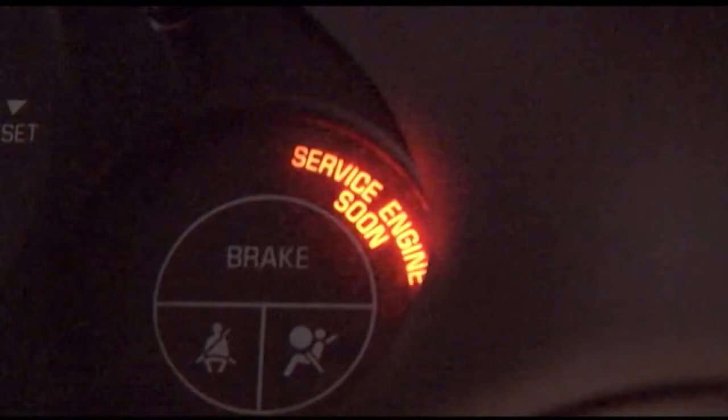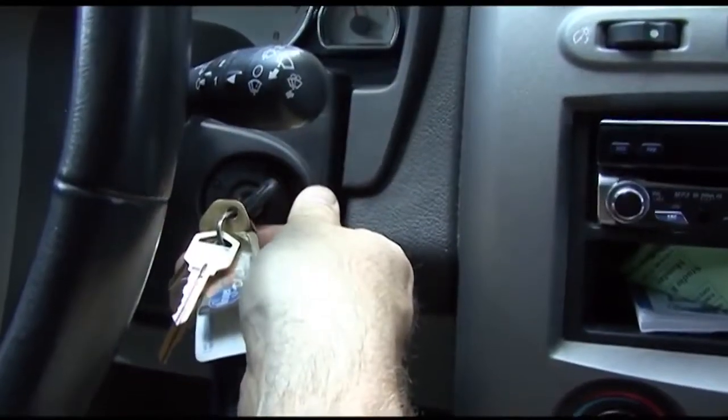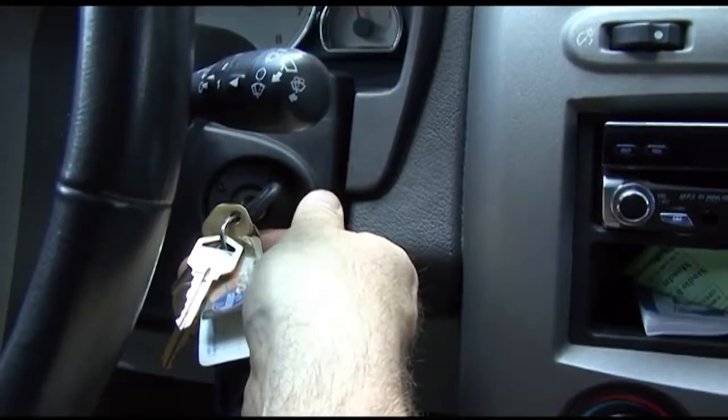Now, let's talk about how you should investigate a no start. The first step is to check and see if the check engine light is on when you turn on the key. Next, check to see if the theft deterrent light is flashing. Can you hear the fuel pump run for 2 seconds when you first turn the key on, and then again after you start to crank the engine? If everything checks out so far, move on to spark and fuel pressure.